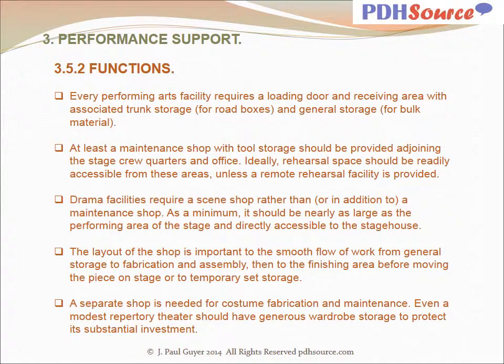Drama facilities require a scene shop rather than or in addition to a maintenance shop. As a minimum, it should be nearly as large as the performing area of the stage and directly accessible to the stage house. The layout of the shop is important to the smooth flow of work from general storage to fabrication and assembly, then to the finishing area before moving the piece on stage or to temporary set storage.